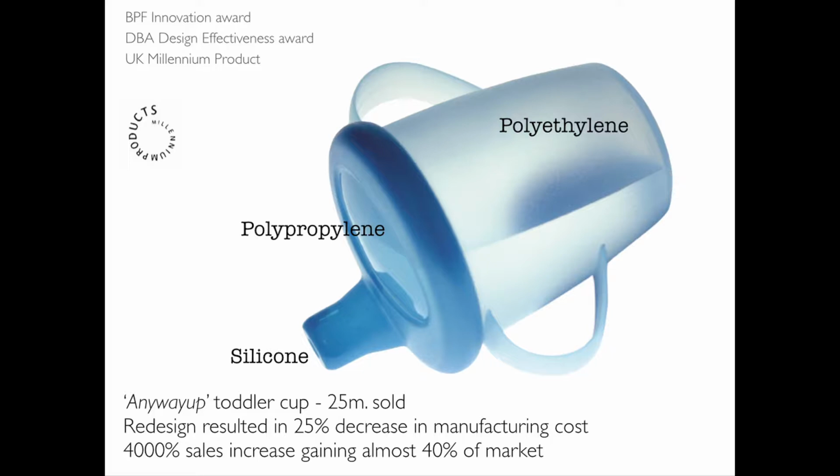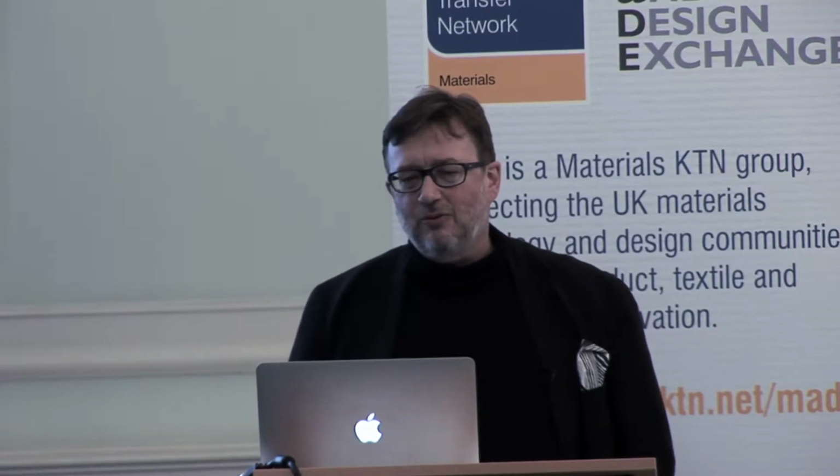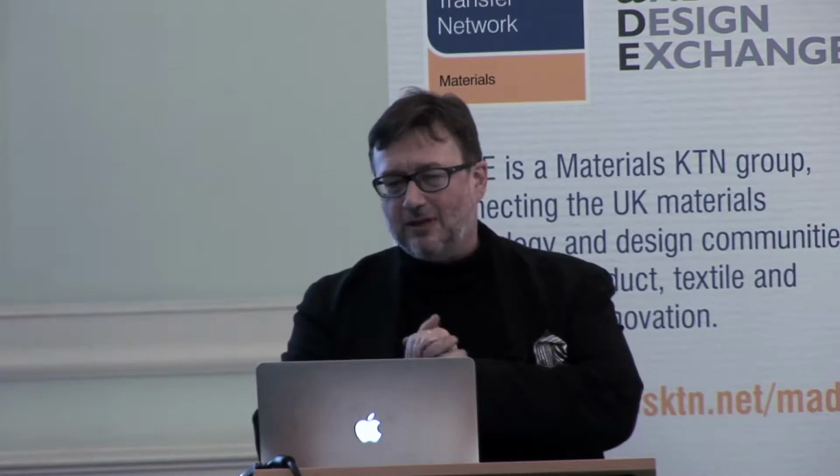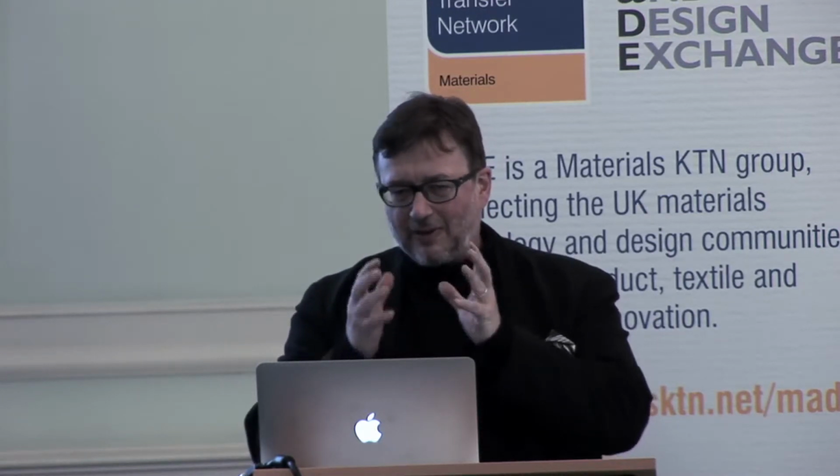But what we did is actually, I remembered somewhere that Earl Tupper's patent was based on using a polyethylene lid with a polypropylene body, or maybe it was the other way around. But on this, we used a polypropylene lid because the silicone would bond to the polypropylene when we co-molded it, and we used a polyethylene body, so we would get a good seal where the dissimilar sized molecules would seal, whereas if we used polypropylene on polypropylene, it sticks and it doesn't work.